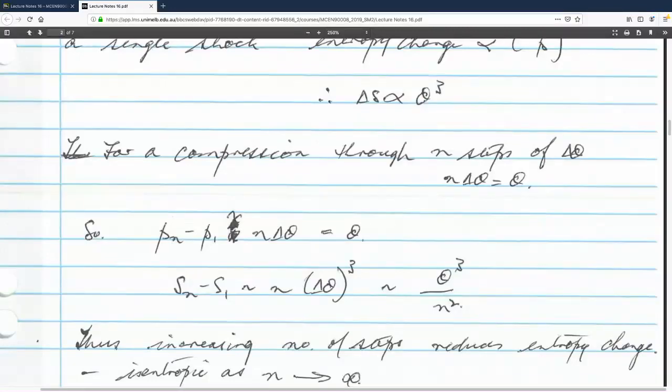Do you understand what I'm saying? You sure? But how do you physically, I mean, if I say that the entropy has increased significantly, what does that tell you physically? I've always struggled with that, from a designer's perspective. If entropy has increased a lot, it'll tell you that the total pressure has gone down. And if the total pressure goes down, then that's a minus for you. You're losing the total pressure that drives the flow.